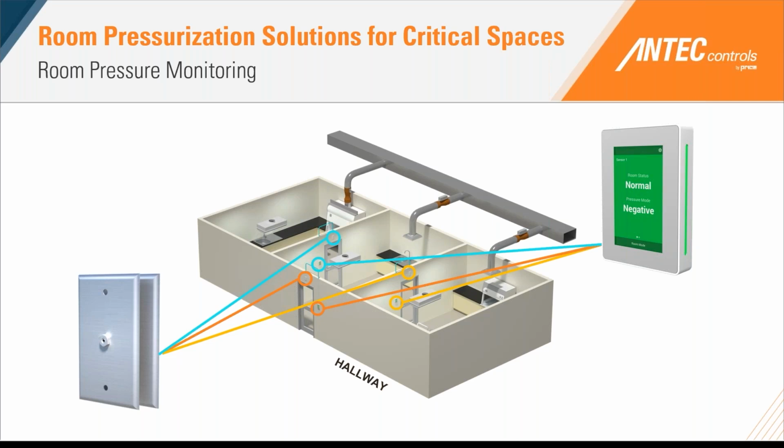Each of these pressure monitors is monitoring a single zone, a single space, and giving you monitoring on those changes happening. So in this type of application, as you walk into the pharmacy, you have 1 display outside the room. As you're inside the anteroom, you can see on both displays what the readings are of those spaces. Now, this isn't a requirement.